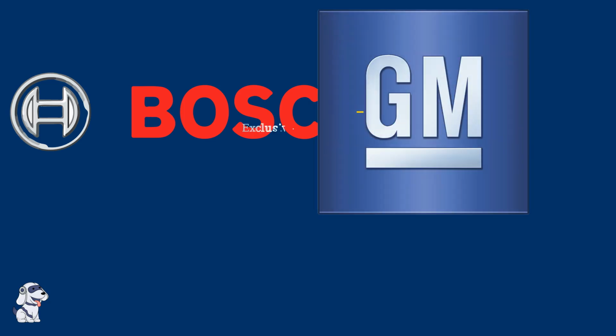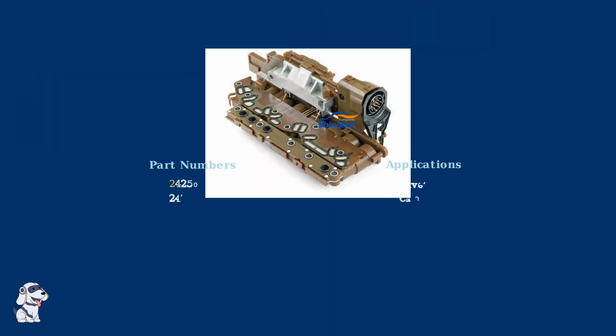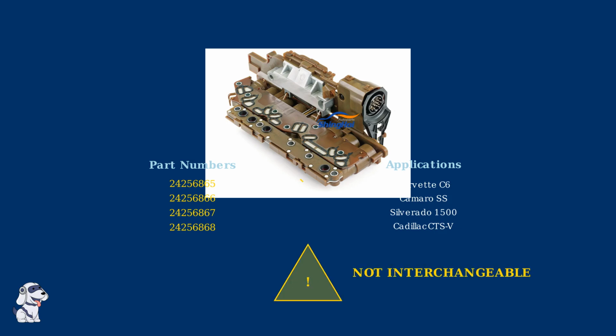Understanding TEHCM manufacturing and interchangeability is crucial for proper diagnosis and replacement. All 6L80 TEHCMs are manufactured by Bosch specifically for General Motors. However, this manufacturing relationship creates an important complexity. Different 6L80 applications require TEHCMs with different part numbers, and these units are typically not interchangeable between applications. The critical point to understand is that these TEHCMs are application-specific. A TEHCM designed for a Corvette cannot simply be installed in a Silverado, even though both use the 6L80 transmission.